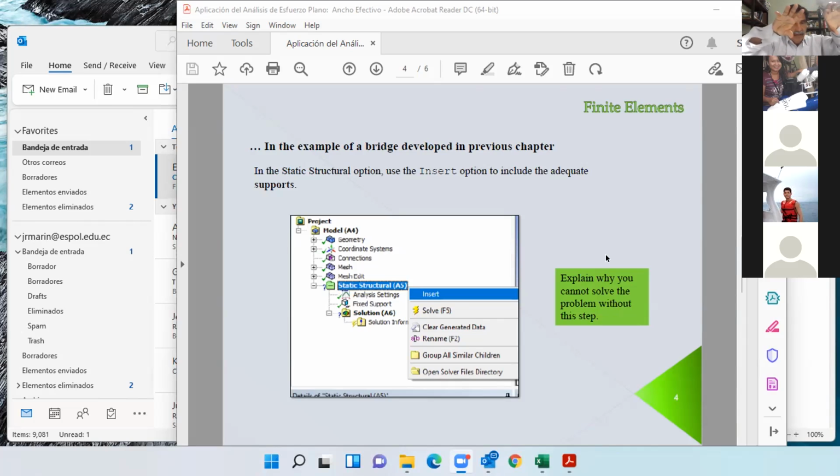As you move it, the solution is different because the values of the displacement are different. But since you do not change the deformation, the stresses inside the structure do not change. But you have many solutions. That's what the program is telling you. In our class we said we have not enough boundary conditions, or the program says that you have rigid body motions. So the solution is not unique. That's what they're telling you.